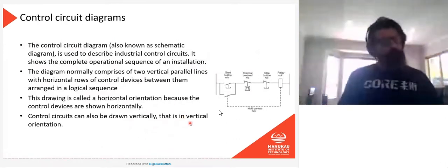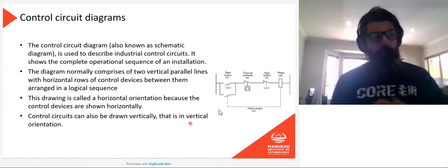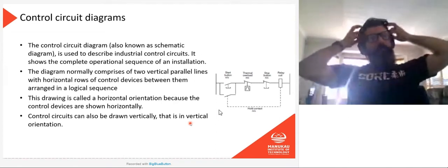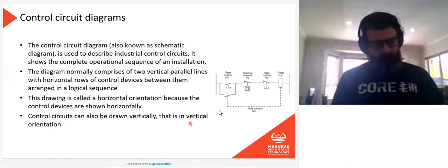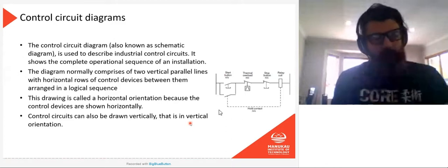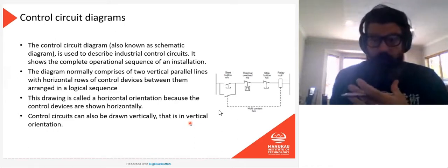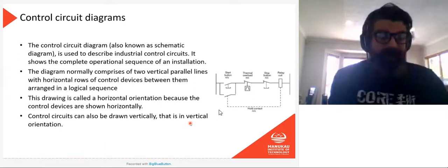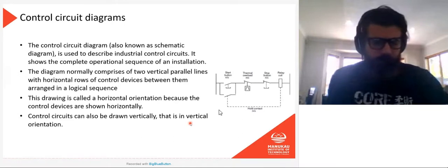Control circuit. Well, let's start with what is a control circuit. So the kinds of circuits that we'll be familiar with at this time, our control and power circuits are essentially the same thing. So what we mean there is if I have a cable, a conductor coming from a switchboard, for example, going through a circuit breaker, through a cable to a light switch, through that light switch up to my light in a room, and then the neutral returns back to the switchboard.